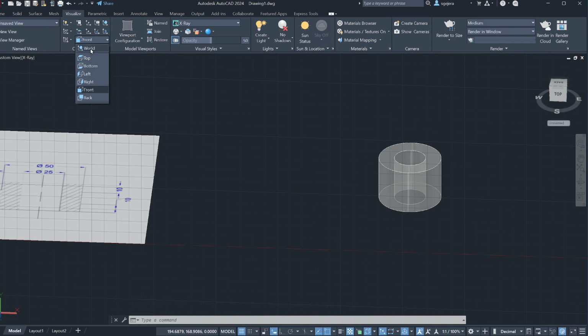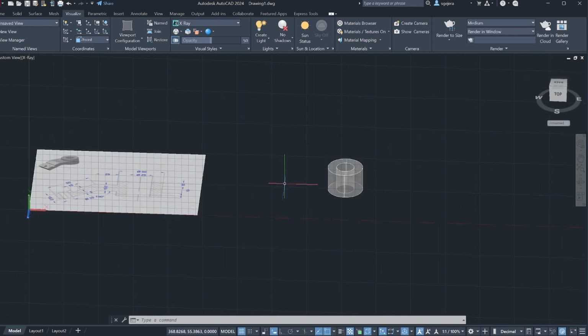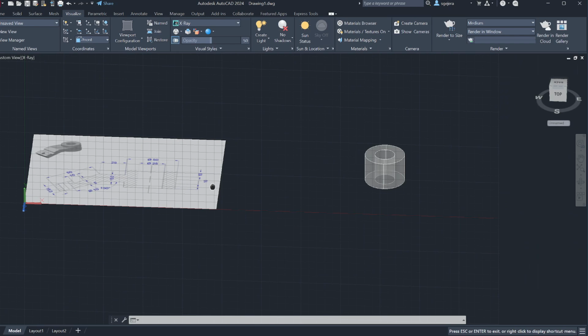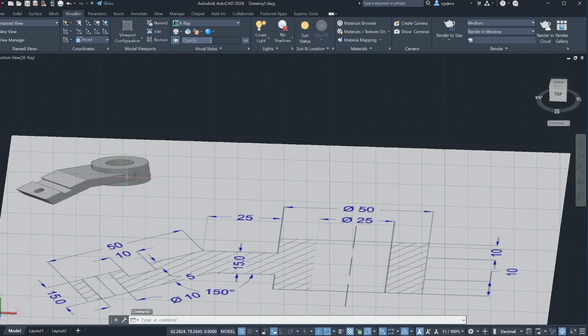So for example, here we have World, Top, Bottom, Left, Right, Front, and Back. Since I'm working on the front view, essentially the front, oh no, sorry, this is not the front view, because this should be the side view. Right? Because if we did it in the front, we would be pulling towards there. Then our side view becomes our front view, which we don't want. So we should do it on the right side view. Because this is our front view.